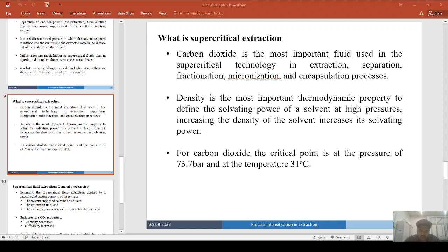Carbon dioxide is actually a non-toxic substance which acts as a solvent, co-solvent or anti-solvent. It can perform the extraction process at extremely high pressure, and can be used for the extraction of bioactive compounds. Carbon dioxide has a critical temperature near room temperature, contributing to the operating conditions, pressure and temperature, to extract thermolabile substances such as bioactive compounds.